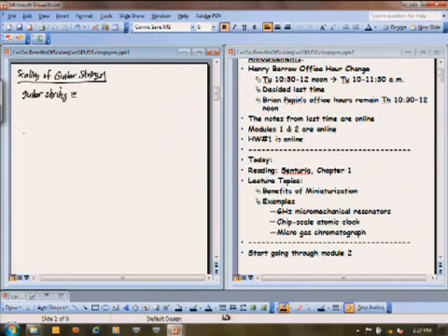Okay, but in a lot of mechanical problems, you have to worry about what kind of boundary conditions you have. And so there's all sorts of different boundary conditions in mechanics. There's fixed-fixed or clamp-clamp. There's simple supports. A guitar string is using a simple boundary condition, which is often drawn by these little pivot triangles here. And so what this is saying is that this boundary condition is such that the motion in the z direction, and so if I come out here and I say this is the z direction,